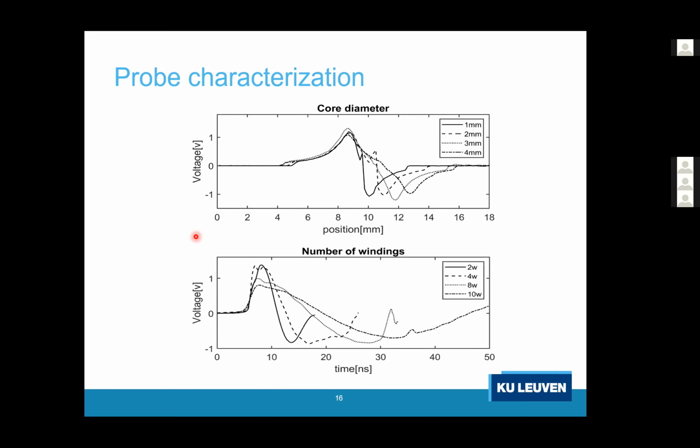And then the last thing that we varied was the number of windings. If you change the number of windings, but everything else stays the same, so the energy that's released by the capacitor will be the same, but your inductance will increase. The higher your inductance, the lower your voltage will be, but the wider your pulse will be. And so with playing with all these different components, you can shape the pulse generated by your device such that you can target individual clock cycles, or target multiple clock cycles at once, depending on your needs.